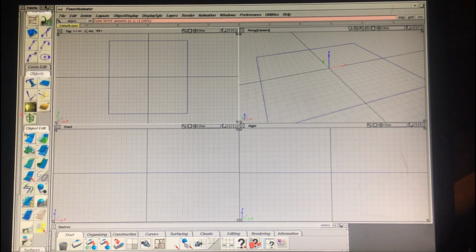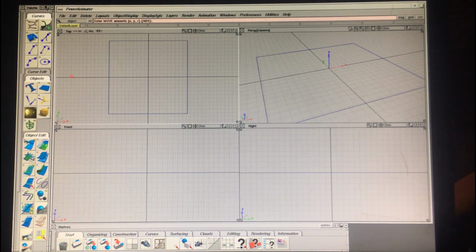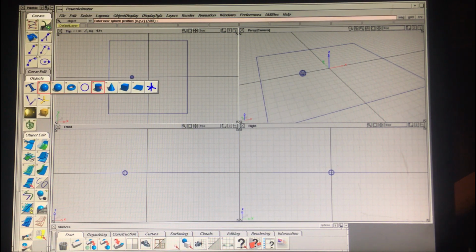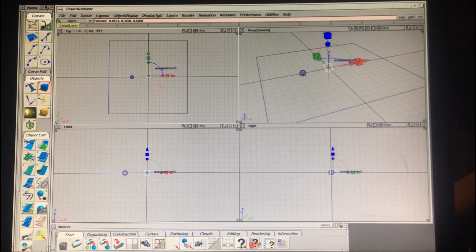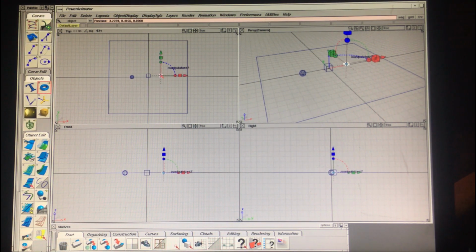That being said, we'll go back down here to the create objects, and we're going to get a few things. So we'll click and hold left click down on the item again, and let's grab a sphere. I'll just click a single sphere into the scene here, and then I'll use that Control Shift left click for nothing, and then we'll go over here and click and hold, and let's do a cube. Put a cube in there, click and hold, and we'll put a torus in here. And we'll have those three items.